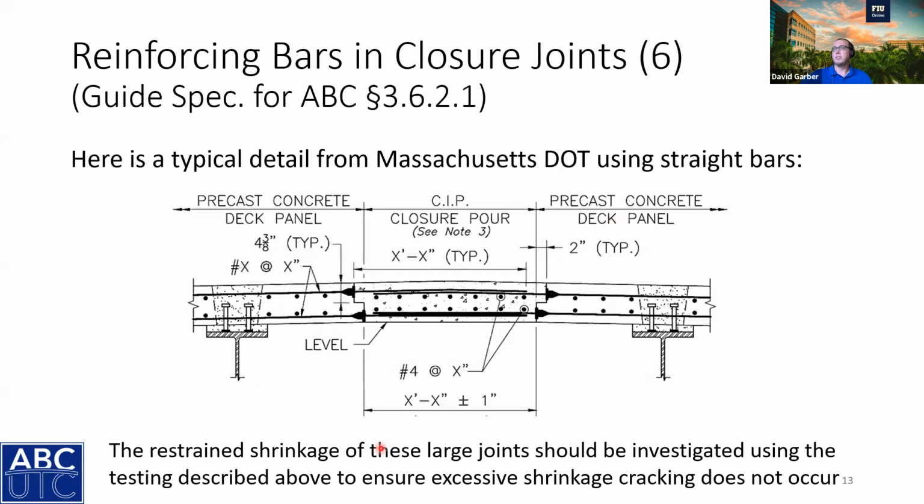Here is a typical detail from Massachusetts DOT. You can see they have the bars extending from each, and the width of the joint would be dependent on the required splice length.